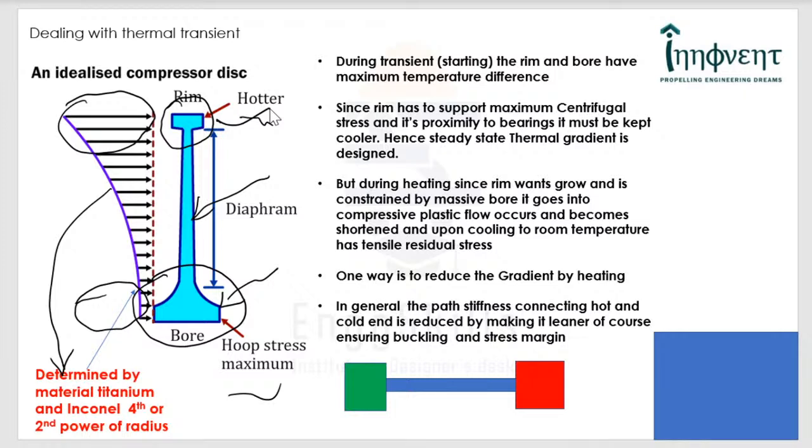As a consequence, you will have to deal with the transient thermal gradient, because evidence has shown that if you deal with it successfully, then the fatigue life of the disc can be improved almost 3 times. That's a very mind-boggling number, but indeed it is true. Now, what are the best practices?